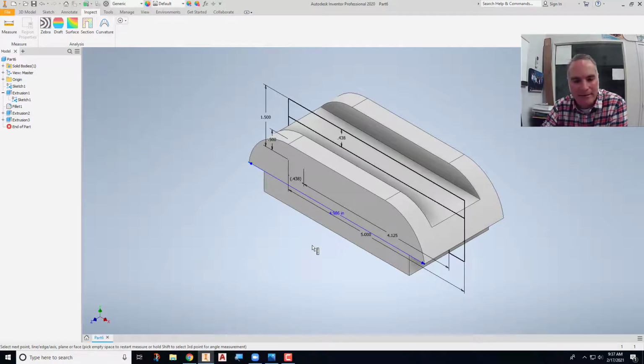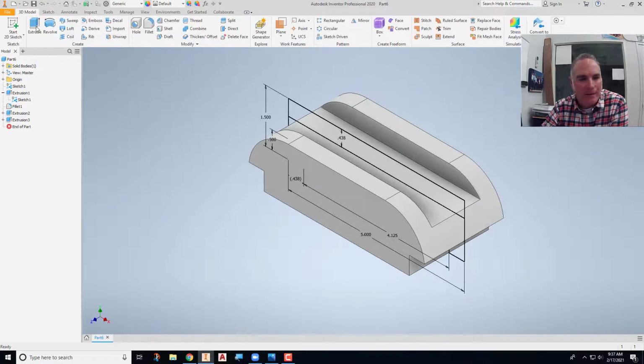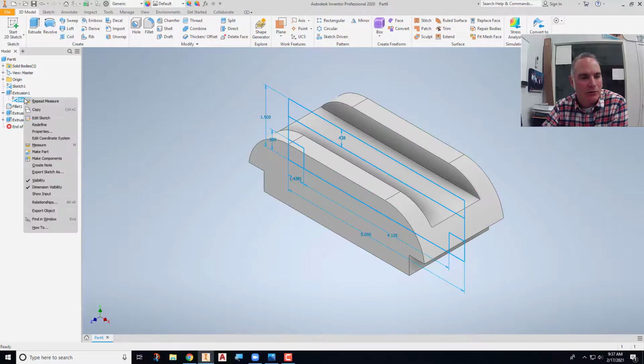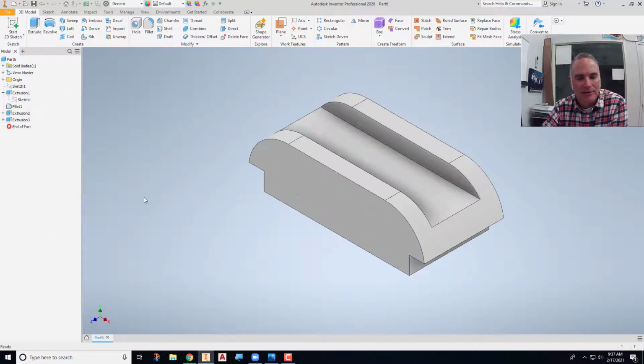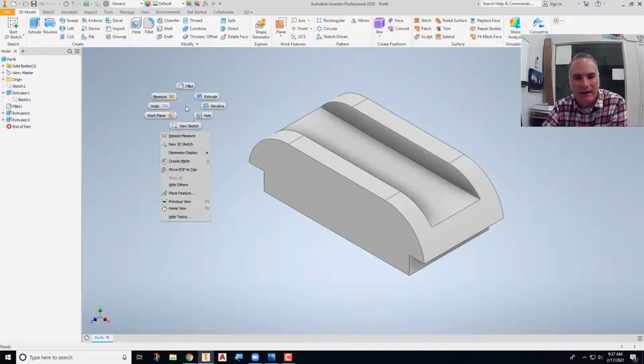But it has to be, because if I make it exactly 5 inches from corner to corner, then this piece right here would not be necessarily the right length anymore. So remember, this one right here is critical. That one has to be 4 1/8 in order to get it to work. So at this point now, I can come back in here, turn off the visibility for this sketch, and then put my final sketch in.